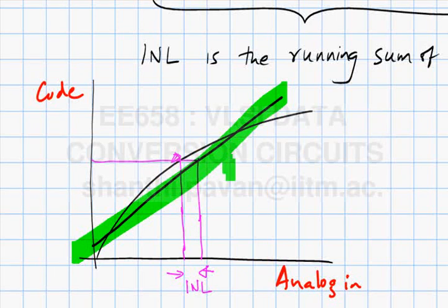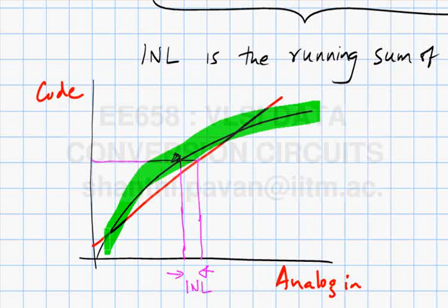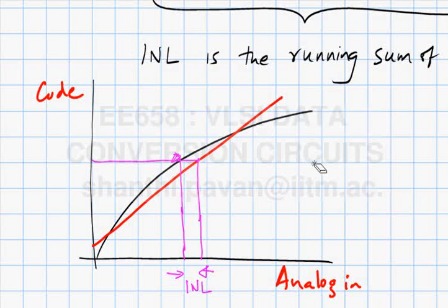But if I have a converter whose characteristic looks like this, you will see quantization noise corresponding to round off, but you can clearly see that this would also result in harmonic distortion. So looking at the INL will give you a reason, and if there is a lot of INL, you can expect a fair amount of harmonic distortion.